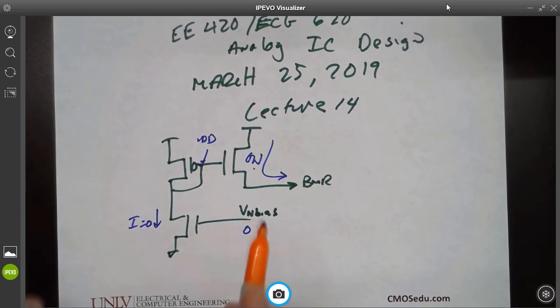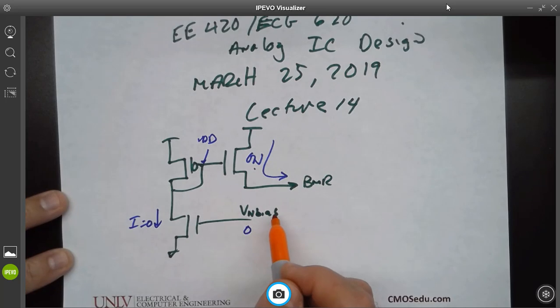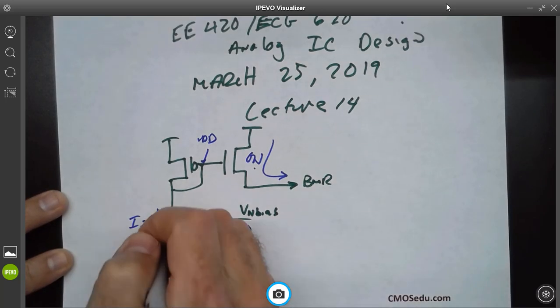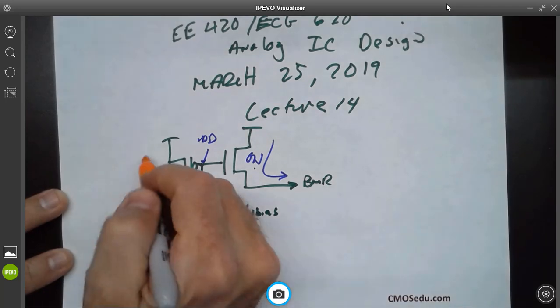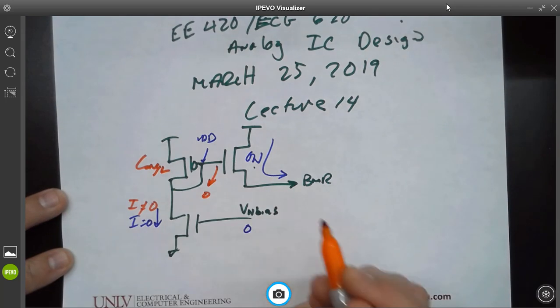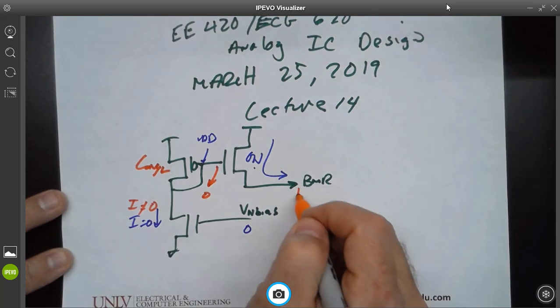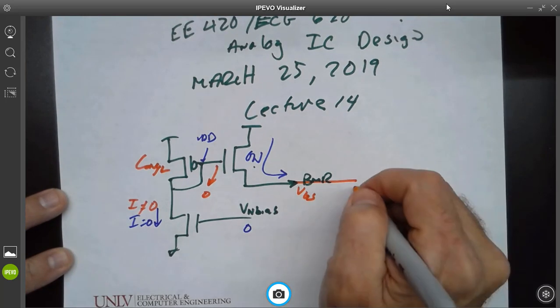Yeah, all right. So this goes out, and the current starts up, and then this goes up to V bias, right? So then I get a current through here that's not equal to 0, right? So what I want is this to be a long L so that the voltage drop across it goes towards ground. Now keep in mind, this is at a VGS where it's connected over into the transistor.